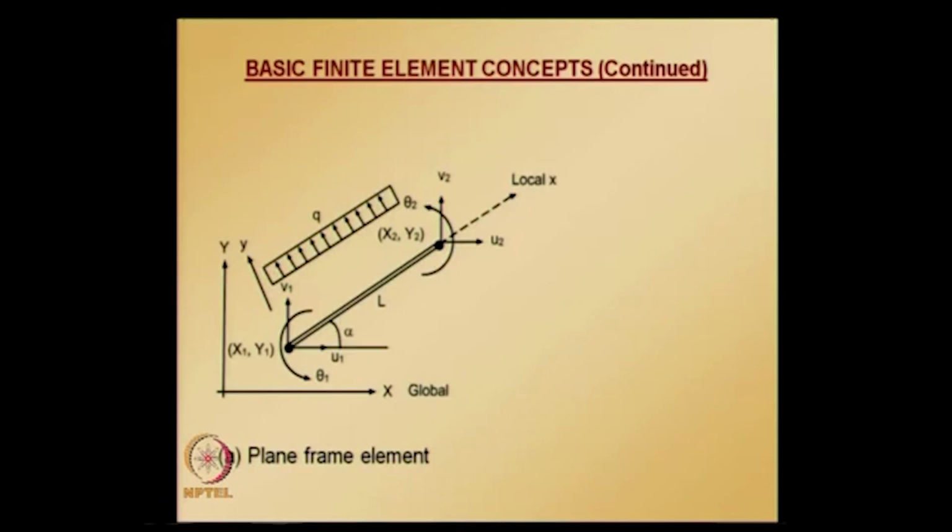The applied forces and moments are assumed to be positive along global coordinate directions. The distributed loads applied over an element are positive if they are acting in the positive local y direction. Positive directions for internal forces, moments and shears are shown here,